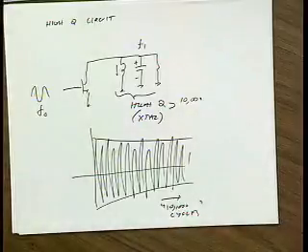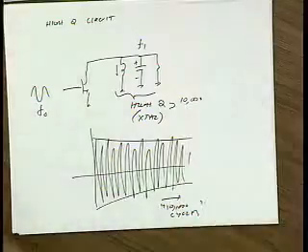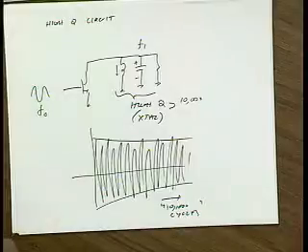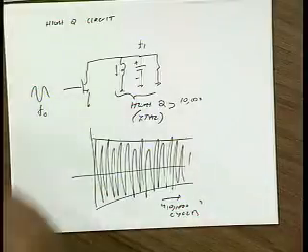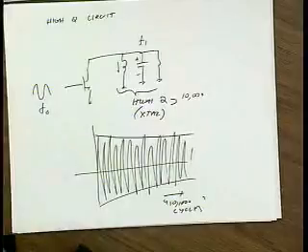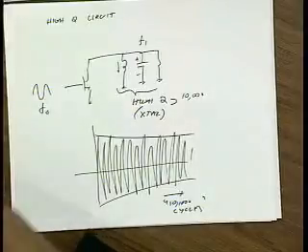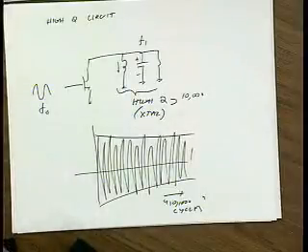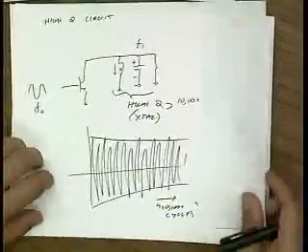Before the circuit gets into steady state, we're not interested in the behavior before? That's also a good question. We may be, in which case we have to run transient. But a lot of times we're interested in the steady state. For instance, you turn on your radio. You don't care what happens the first 1 microsecond, right? You care about the steady state once the radio is working. So that first 1 microsecond is actually dead time. We wish we could make it shorter, but sometimes you can't. Okay?